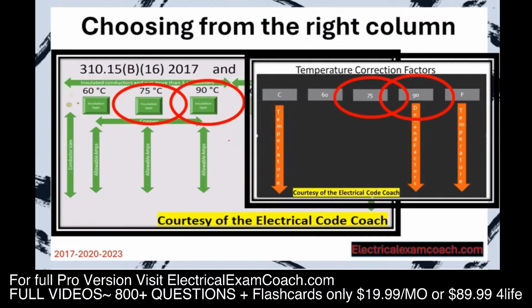And one thing that I do want to mention at this point in the program is NM cable. NM cable is Romex, and it is actually allowed to be chosen from the 90-degree C column. Romex is just a trade name. They also have Southwire and other trade names. But in the code book, it's called NM cable. And for the purpose of bundling adjustments and temperature corrections, you're allowed to choose from the 90-degree C column when doing those calculations.